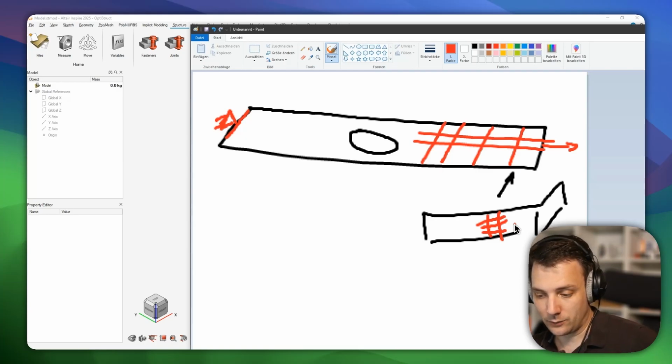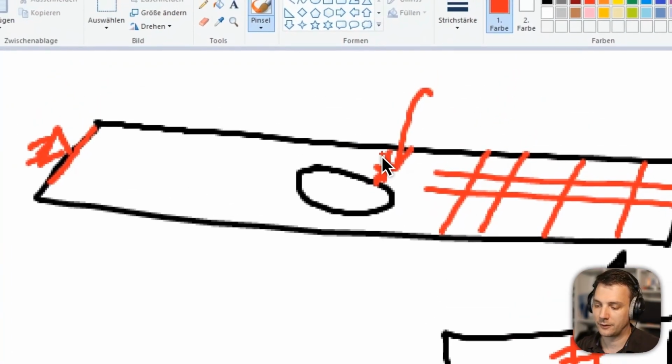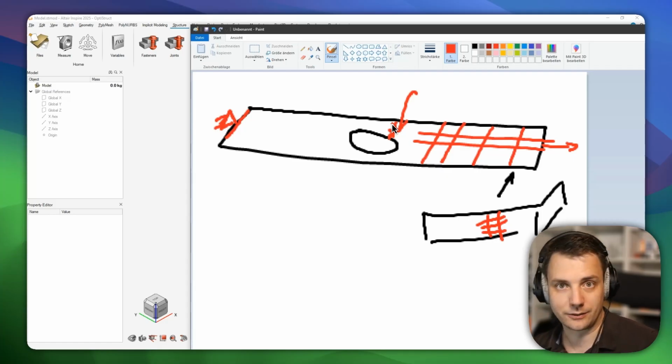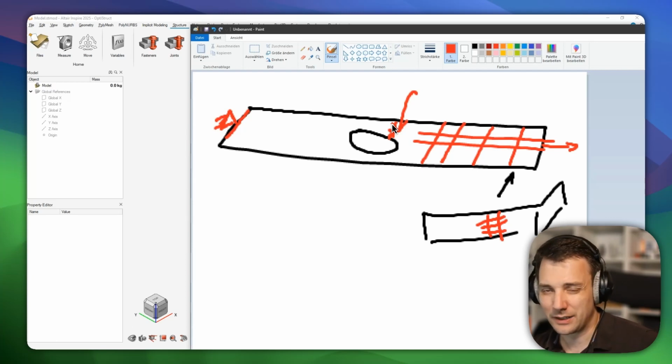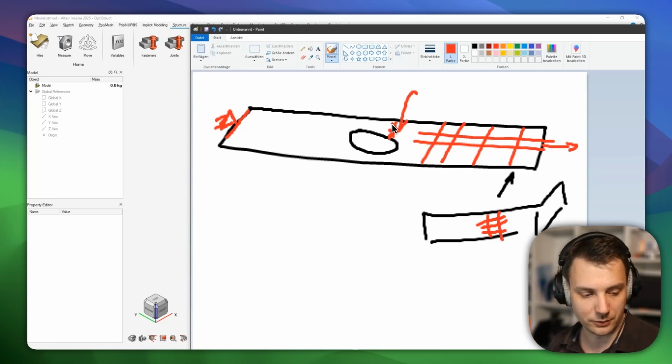That's why you want that, because this allows you to have a finer mesh where you care, compared to 3D, where you will hit the limit of your computation power pretty soon, or you would have to pay a lot for, I don't know, cloud cost or something like that, which is not really necessary. So simplifications like this, going to a 2D mesh, is a great technique and should be applied if it's possible. So always check if it's possible to do those.